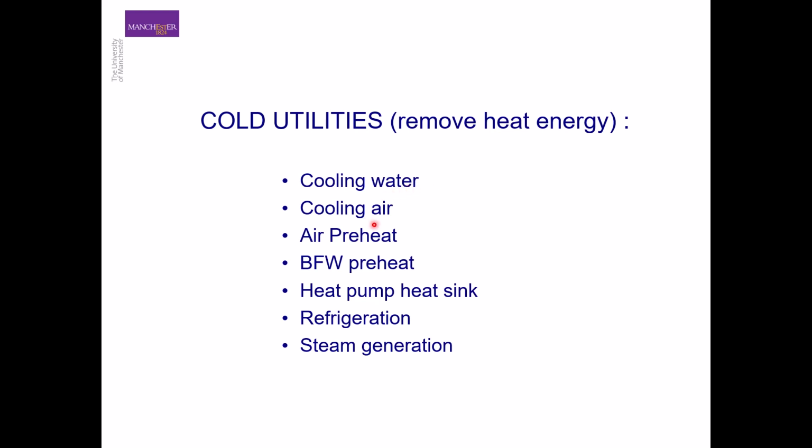Then we can have cooling air as a cold utility, but cooling air is a kind of limited use cold utility because the temperatures of the cooling air available significantly depend on the location of the plant. So if you are in a cold country, you can use it as a cold utility, but if you are in a warm country, then you will have limited effectiveness of this cooling air.